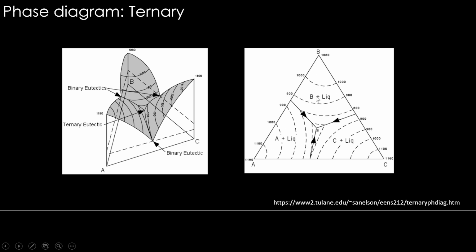So this sort of marking can also be done sometimes. And these lines, more importantly, are the eutectic lines. You see this curve which is going from here down towards the center. This, if you see from the top, is going to look like a line like this. Okay, and they all meet at point E, which is the ternary eutectic point. Ternary eutectic point means that liquid gets converted to three solids, not two solids. That's ternary eutectic for you. So this is how the eutectic reactions will look in the ternary regime.